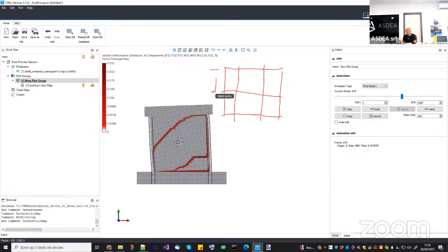So now if we have a finite element which is pretty much the same size as the spacing here, I will have a finite element like this, and then at the integration point, I have a material model which has a percentage of steel pretty much equal to the area of this one. So it still makes the problem pretty similar to the microstructure, equivalent to basically a rebar here and another rebar here. Now, when you keep on refining the mesh, imagine I start having a very, very fine mesh like this.